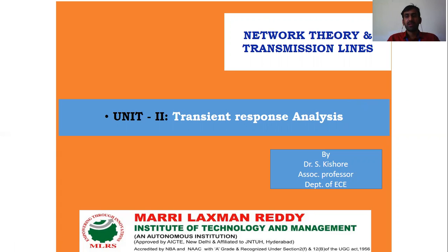It can be linear differential equations, in the form of first order differential equations and second order differential equations. With respect to first order and second order differential equations, we are going to analyze the transient behavior of the series RL and series RC circuits.